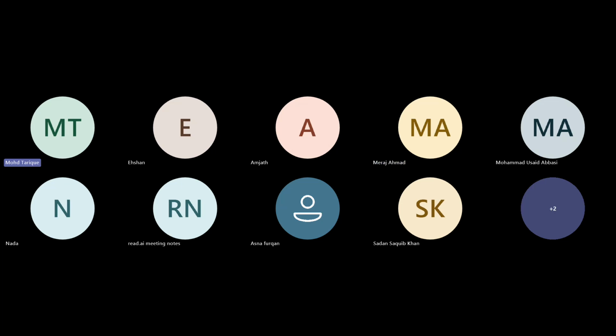My question is, if you have a synthesizable netlist after running this with the same test bench, then the synthesized code can also be used with the same test bench. If the output is the same, then your netlist is almost the same.